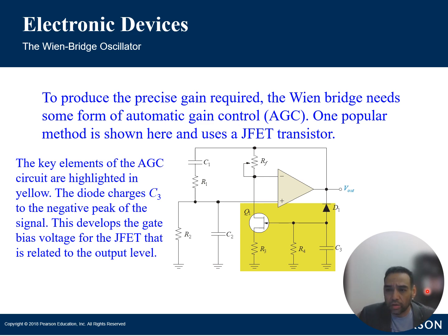So again, tuning the oscillator to whatever desired frequency you want is going to require precise adjustments of those resistors and then those capacitor values. So you don't want to use something like, you'll see the feedback resistor in this circuit, the potentiometer. Those are not very precise, and they vary widely based on the environmental factors.